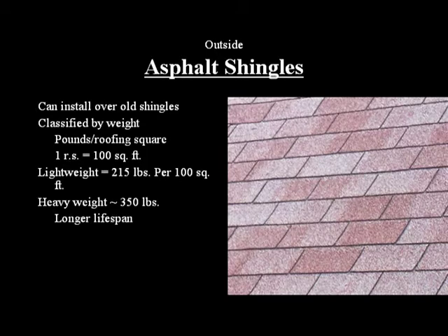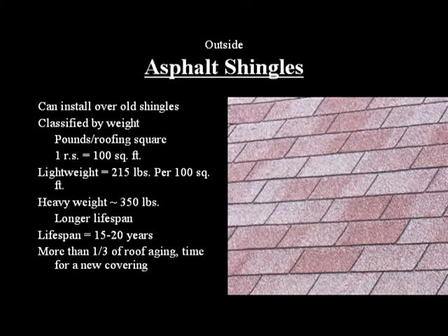Most manufacturers have given asphalt shingles a lifespan between 15 and 20 years. However, proper maintenance of patching and coating exposed and eroded areas can prolong the lifespan a little while longer. If more than 1/3 of the roof has shown signs of aging, I recommend a new covering.